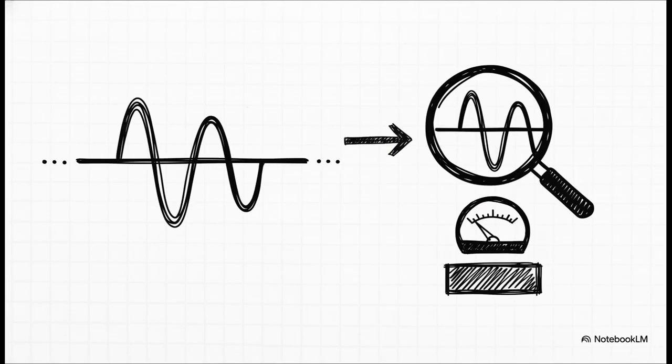Next, we've got a classic sinusoid. Now, for any periodic signal like this one, its total energy is going to be infinite just because it repeats forever and ever. So we don't even bother with the energy calculation. We jump straight to power. And here's a great shortcut. For any sinusoid that looks like A cosine omega t, the average power is just the amplitude squared divided by 2. In our case, A is 3, so the power is 3 squared over 2, which is 4.5. And since that's a finite, non-zero number, this is a power signal.